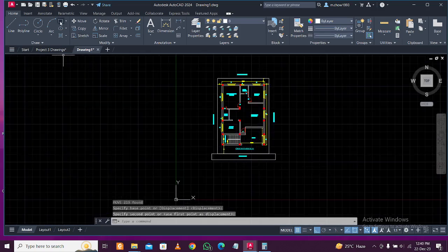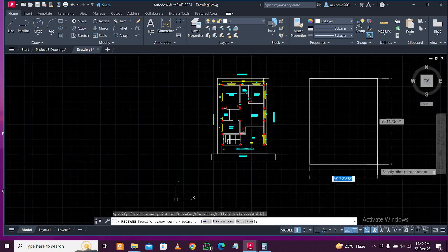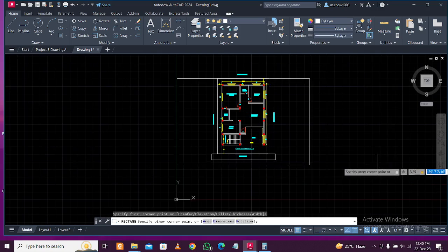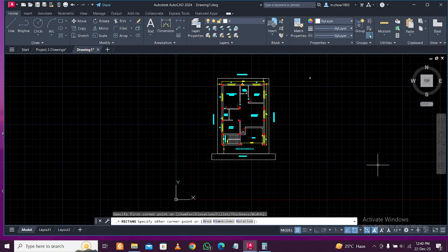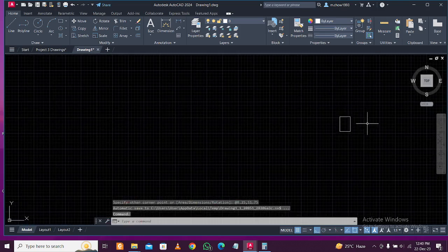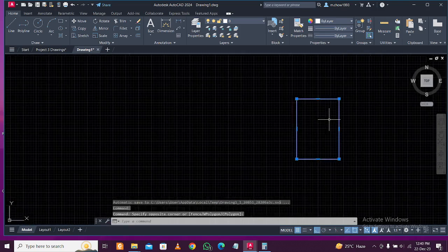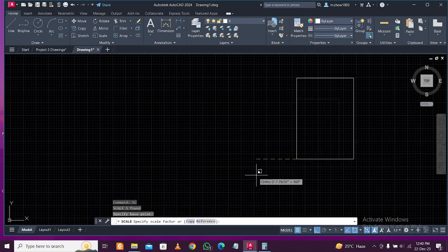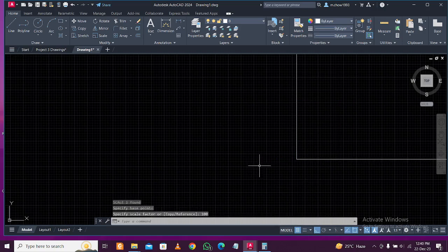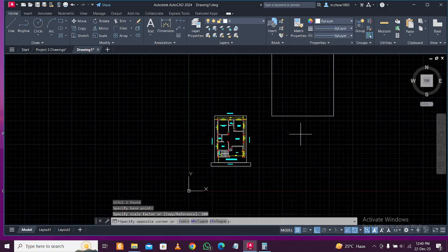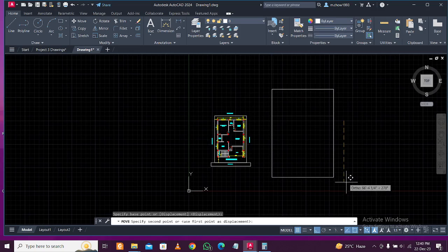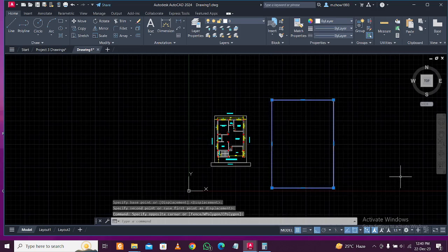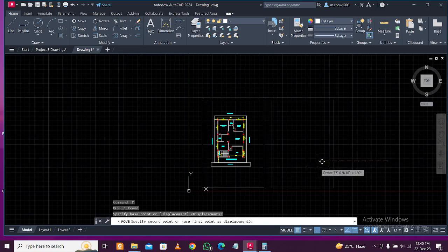a particular box here. So here A4 size is 8.25 comma 11.75 inches. So that's why you use scale. So this is the A4 size, actual paper size. I'm going to scale this. Let's see, enter. Let's scale it to 100 times, and you can see scale 100 times. This looks like this, and we have used 100 scale for the text also, so it will fit in. Okay, it will fit in like this, properly.